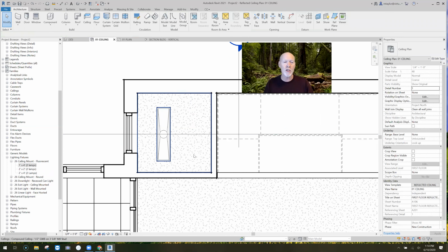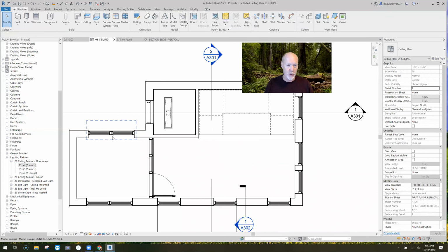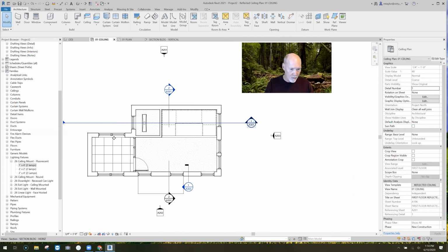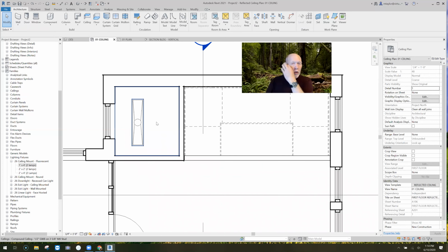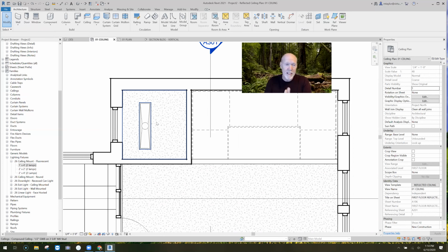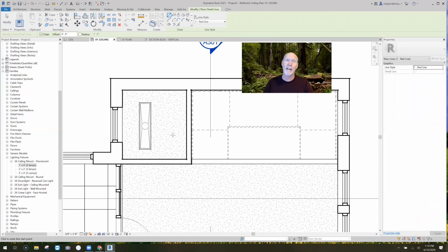There are 2 different ways you can use Revit to center things. I'm going to get this out of the way. So, 2 different ways of centering objects: you can use dimensions or you can use a line. Here's where we go. A detail line is view specific, and I'm going to hit DL on the keyboard for a detail line.